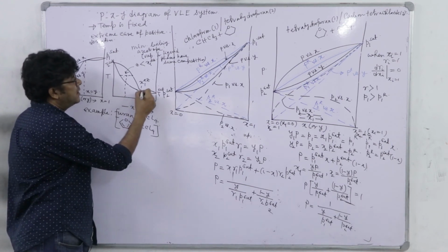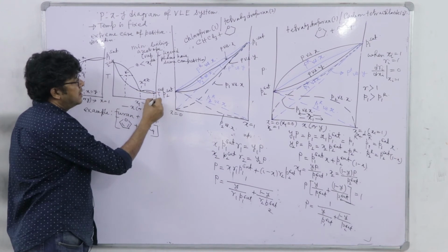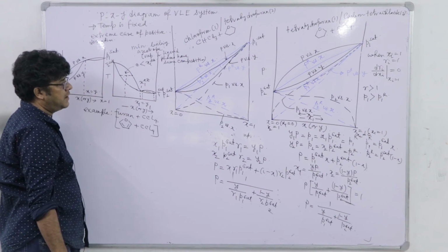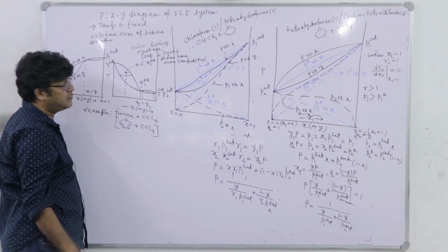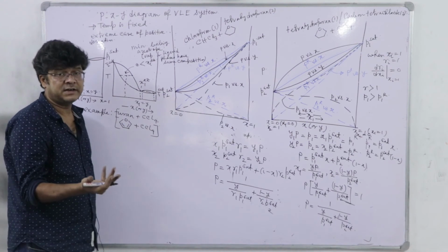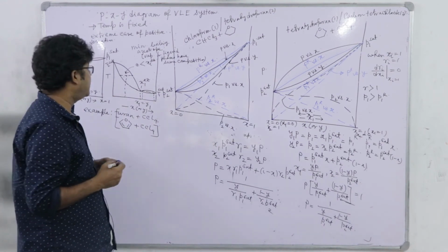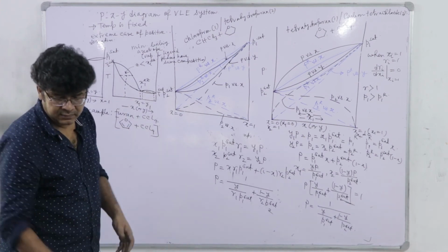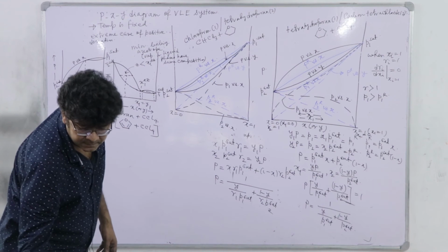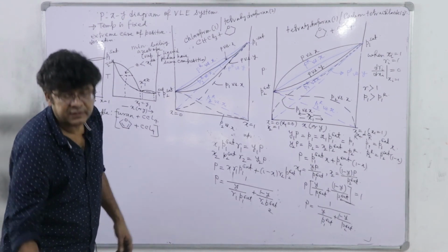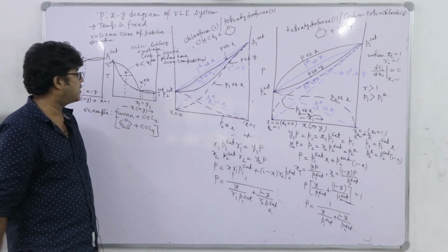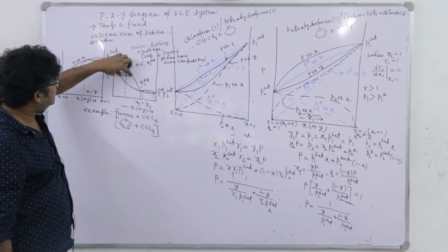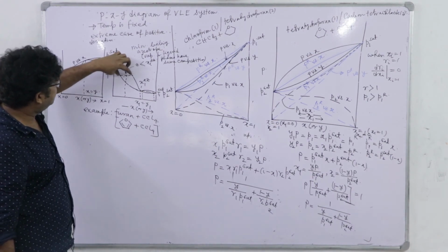But here the liquid phase will be rich in low boiling component, whereas the vapor phase is rich in high boiling component, which is just getting inverted because of this azeotropic composition, right. But definitely this is an absurd case, we don't have rather this feed with composition above and over azeotropic composition, right.